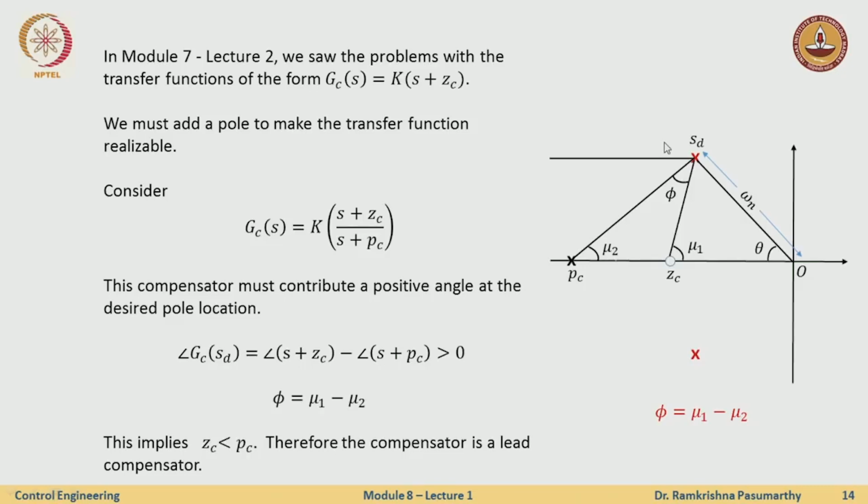Okay. So once I know the effect of adding a 0, there is some drawback here. Can I just go to the market and buy a controller which looks like this? Well, the answer is no, because, as we had seen earlier, this is a non-causal system. Somebody in the message forum also asked, what is the inverse Laplace transform of s?